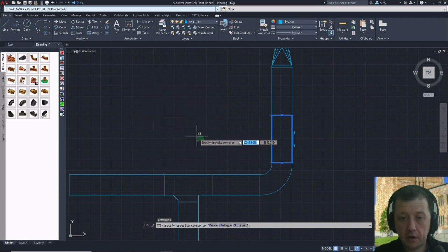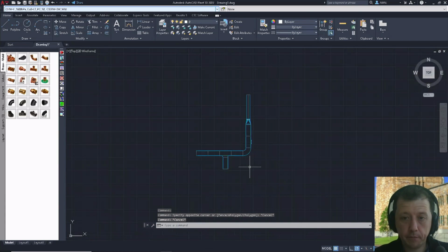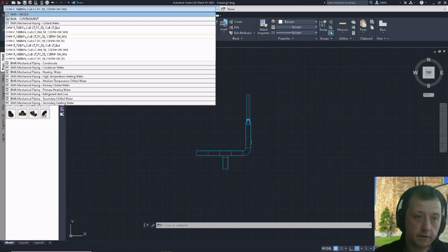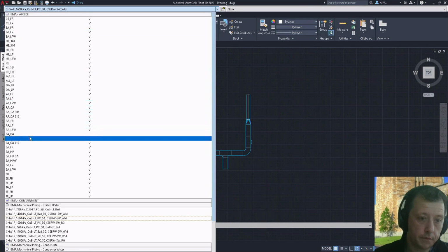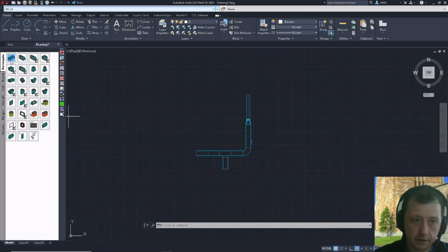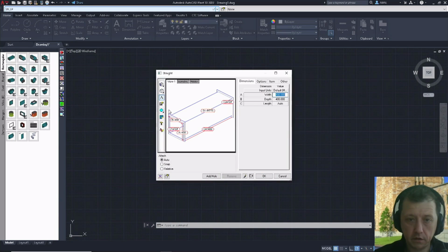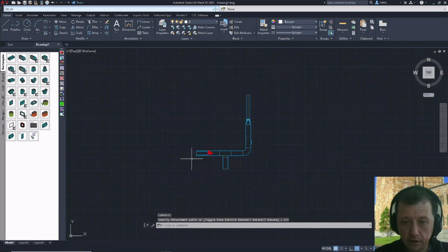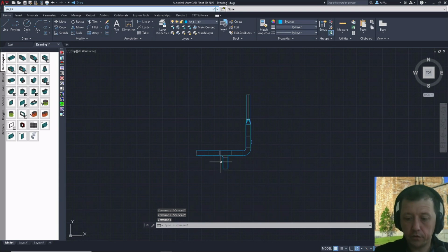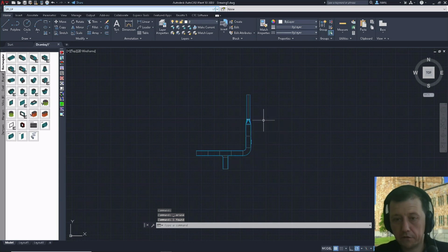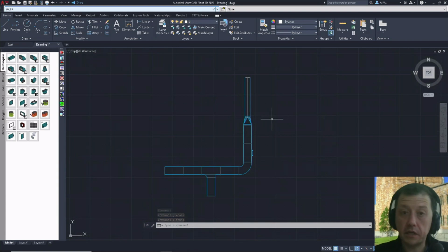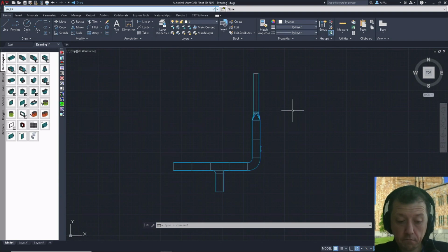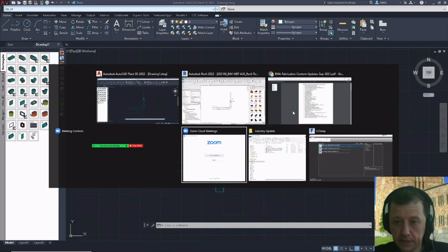So this is how it looks here in CAMduct. You can just select the right system here, maybe supply air again, and you have exactly the same elements. You can just keep going here and add that part now also to your system. You can just keep designing and keep detailing everything in CAMduct if you don't want to do that in Revit. Another tool that Shannon was talking about was SMap.